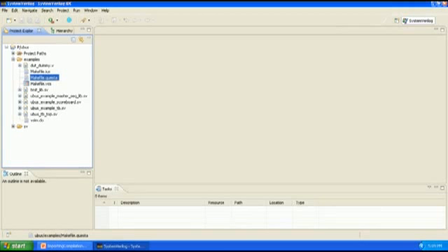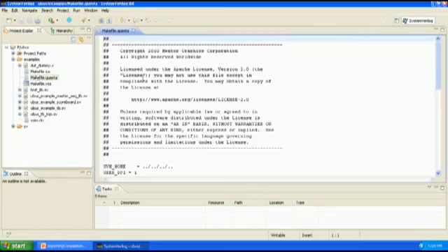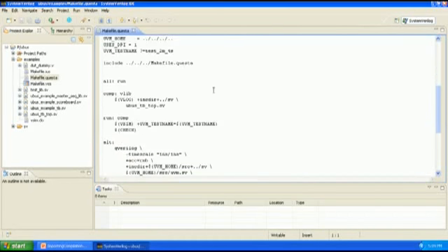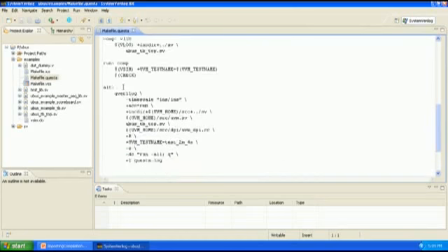Okay, here we have the SVE environment up and running, and we have our standard UVM UBus project loaded into the workspace. Now, notice that we don't have an argument file set up here. But we do have a few make files that are used to build this example. And we're going to use the Questa make file to capture the compilation arguments. Now, for one reason, because we're on Windows, we're going to use this make target down here, the alt target, that uses qverilog to build everything. But we can see something interesting using this target as well.